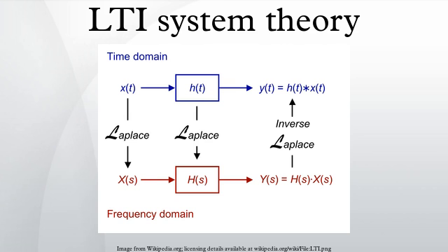In summary, the input function can be represented by a continuum of time-shifted impulse functions, combined linearly, as shown in EC1. The system's linearity property allows the system's response to be represented by the corresponding continuum of impulse responses, combined in the same way. And the time invariance property allows that combination to be represented by the convolution integral. The mathematical operations above have a simple graphical simulation.